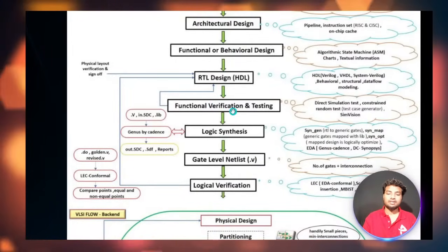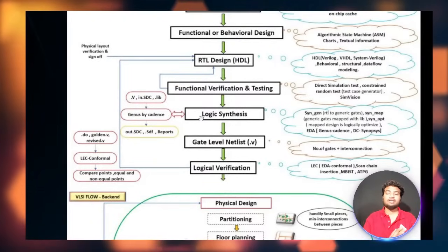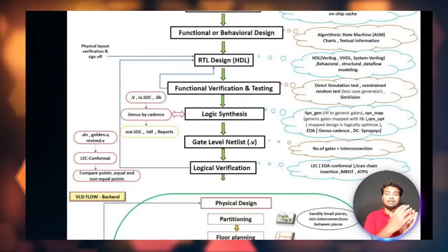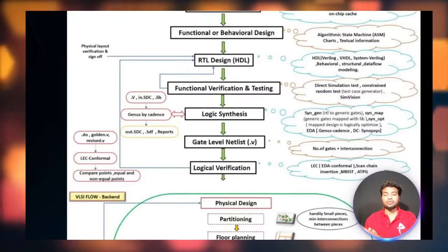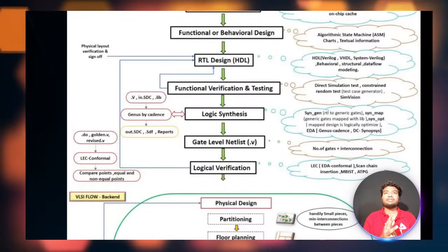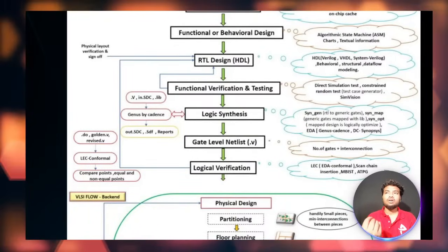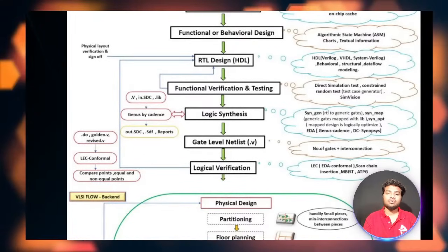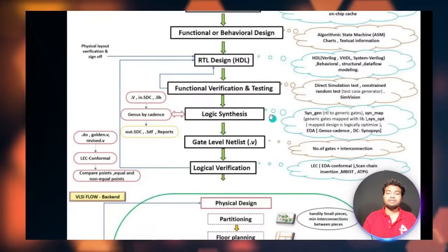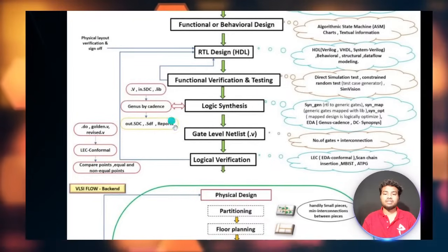Okay, after functional verification and testing comes logic synthesis. It is nothing but converting the design code, like your logic that you have written in Verilog, into logic gate circuits. We are converting the Verilog code into a gate circuit. Why? Because we can't directly implement the logic inside the chip. So we have to convert the Verilog code into gates. That part comes under logic synthesis. One engineer will do it. So this also comes under the front-end engineer.